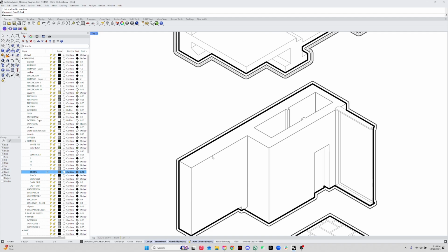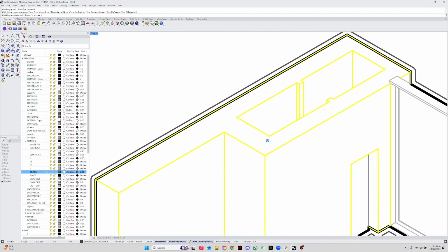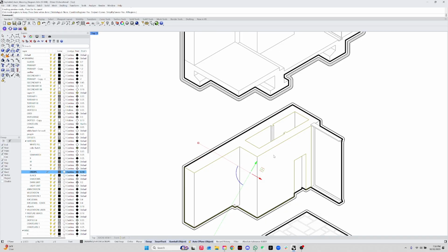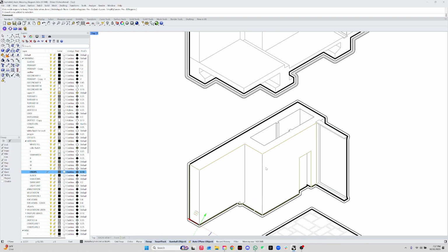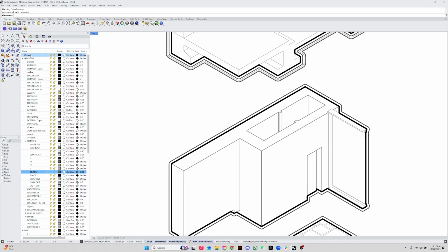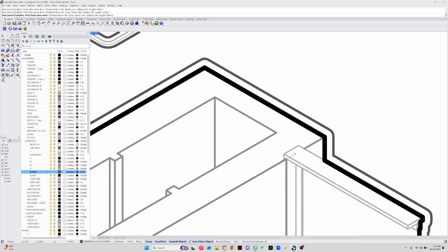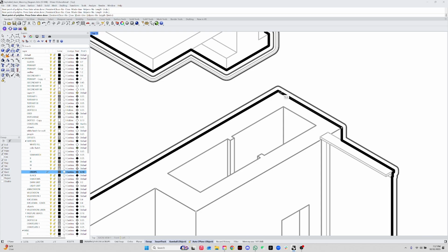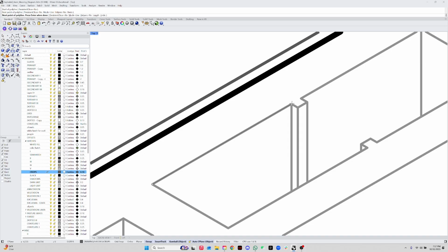Maybe show different, maybe even if I wanted to do something like this where I do curve boolean of this, right? And since this is a wall that's being sectioned off from there, obviously you need to make sure that your lines are completely closed to do that. So for me, it was not the case. Worst case scenario, if you don't want to spend the time fixing it, you can just draw the profile like this, super quick, just to give you a hatch pattern. And then I'll go like this, the same thing, go like this.